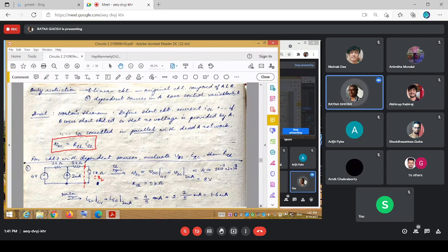Okay, and R Thevenin is for the dead network. Dead network means this is open, this is short. So you're looking in from this side. This is open and this is shorted, right? So that being so, what do you have? You just have 3 kilo ohms plus 2 kilo ohms. So that is 5 kilo ohms. That's your 5 kilo ohms here.